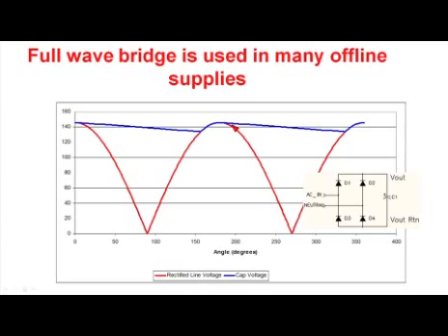For instance, if you had a smaller capacitor in your circuit, it would discharge more, and you would end up having to operate with a lower input voltage. A larger cap reduces the range that your power supply has to operate over. That's important because that sets the turns ratio in the transformer, and it sets many of the circuit stresses. The higher that the input voltage needs to be for the power supply to operate, the more efficient the power supply is.